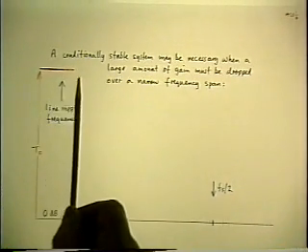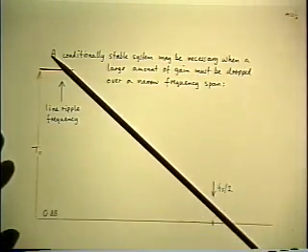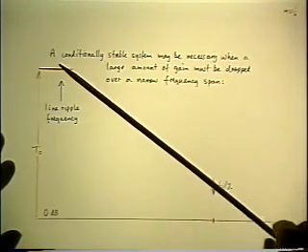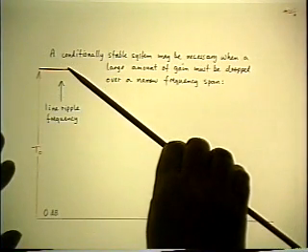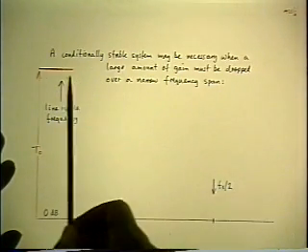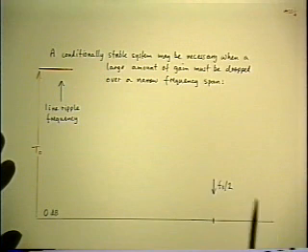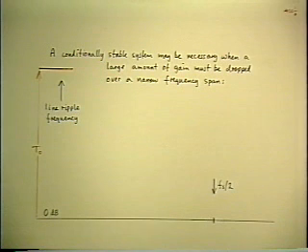Now this gives me a window of frequency in order for the loop gain to go away. It's going to go to zero ultimately. But if I put a single pole starting at 20 kilohertz and I have to throw away 40 dB of feedback, which is a factor of 100, then the crossover frequency on a single slope is going to be 100 times 20 kilohertz, or 2 megahertz. Now, I can't permit that because I'm not going to be able to control the parasitic capacitances all the way up to 2 megahertz.